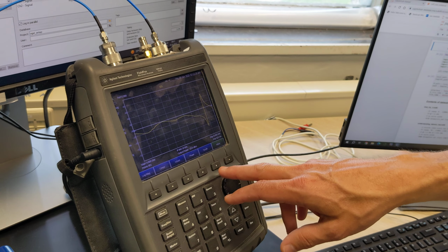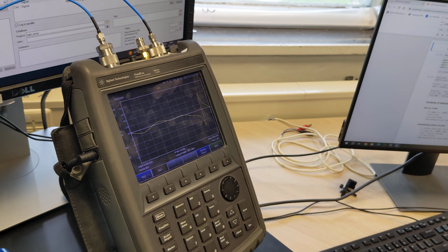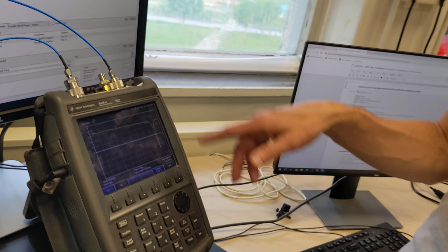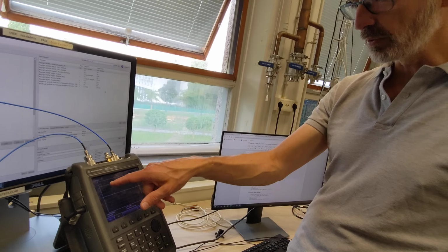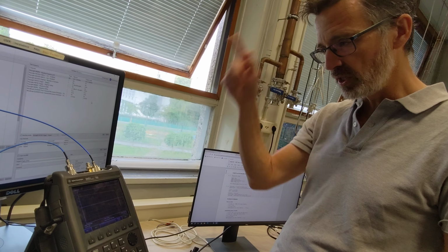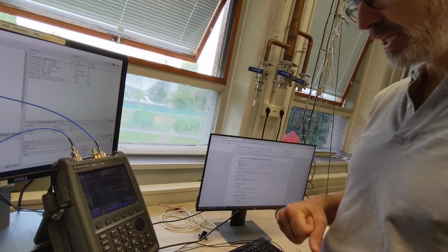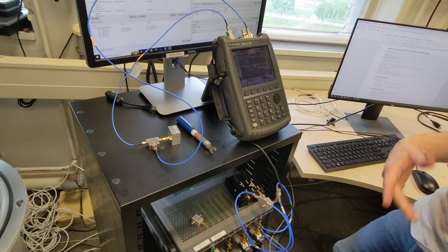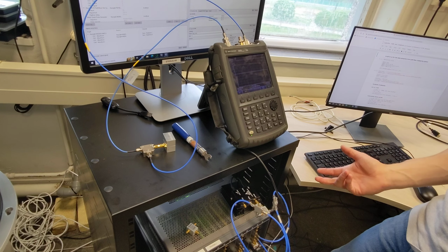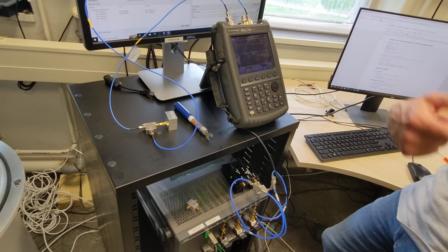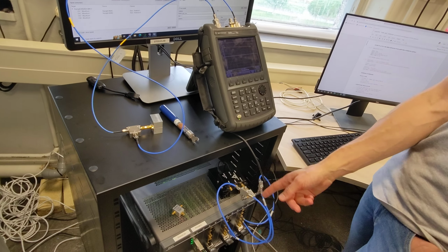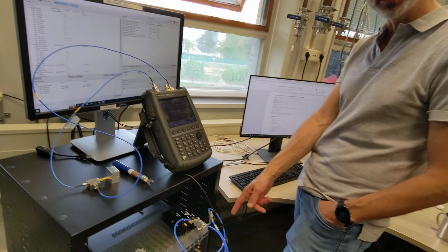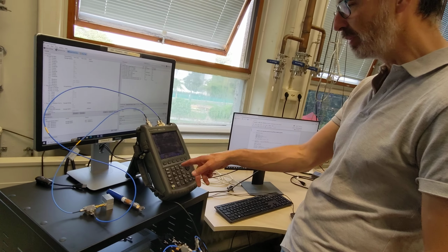So if we do everything correctly, including probably a software correction in Python with the plotting to correct for the electrical length of the cables, then we should be able to see something that reproduces this. Now, the only thing is our analog bandwidth. If we do the IQ modulation and push the limits of our IQ mixers, we can go plus and minus 400 megahertz. Actually, the thing has a specified analog bandwidth of 200 megahertz, is it, of the Keysight? Yes. Okay, so we can go plus or minus 400 megahertz.